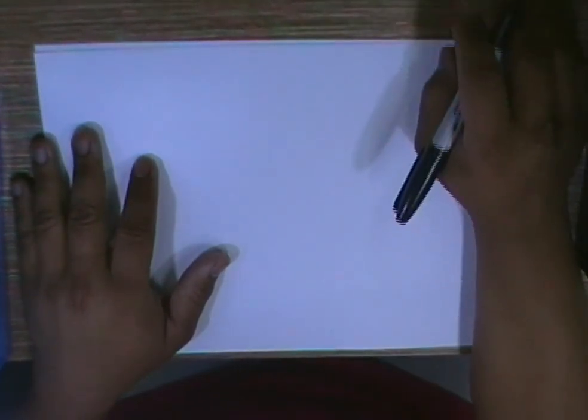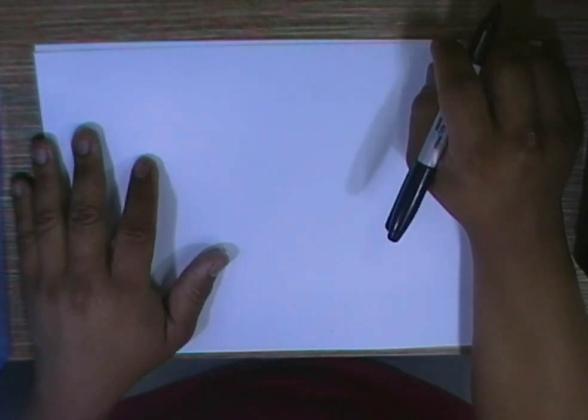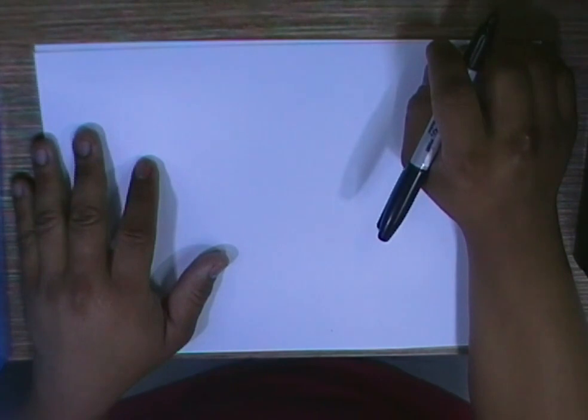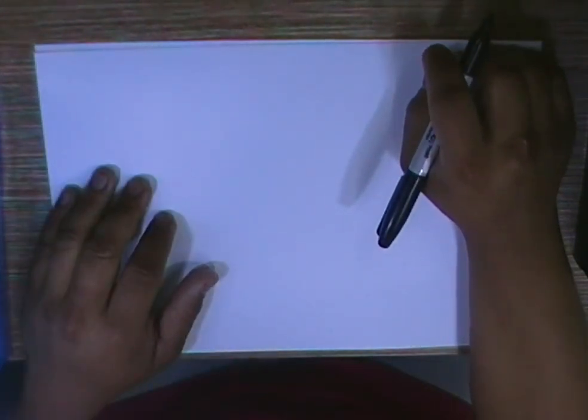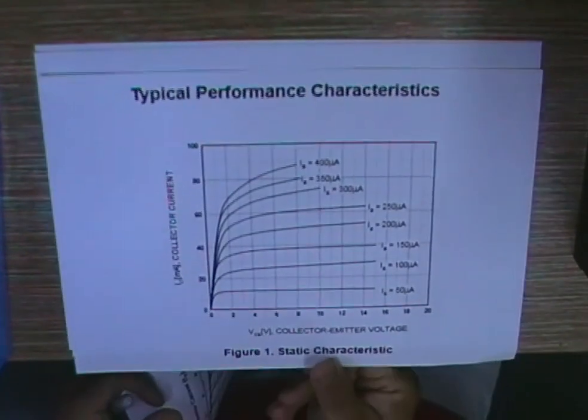Just have to set the VGS so that the gain that you desire will be adjusted according to the RD, and the current will be set by VGS. It's very straightforward. But for BJT, the design process is a bit tedious. Before we can start with the design process of BJT, you need to understand a few things. The most important thing is the characteristic curve of a transistor.